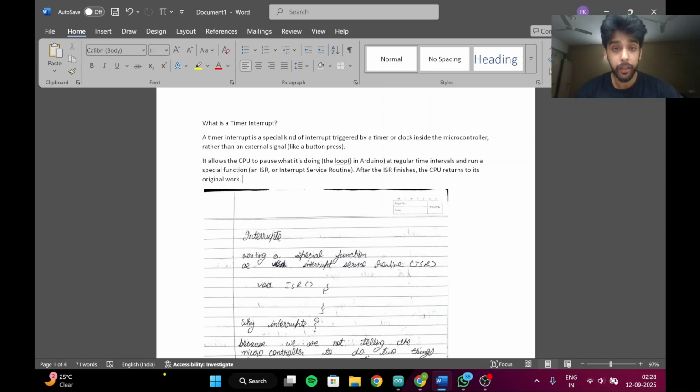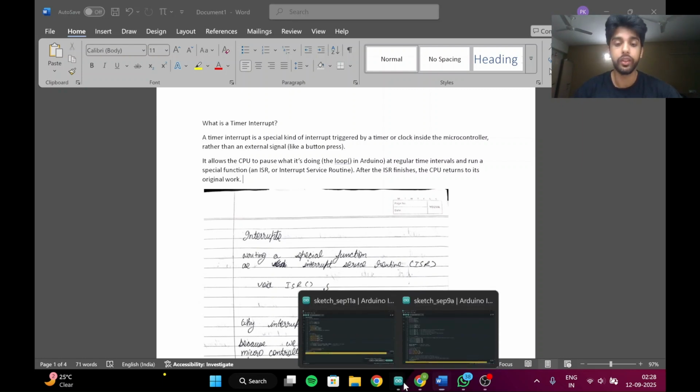This is one of the main features of the internal interrupt, that it is periodic because it can be fired after a fixed interval of time. And the second main feature which distinguishes it from the external is it doesn't require any pins because it is fired internally by the serial clock, and that's how it is working. So let's move on to the code.